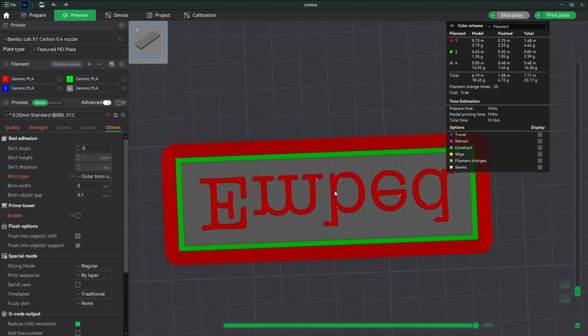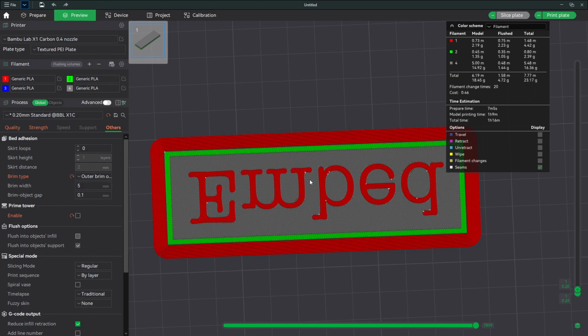It just depends. I had one earlier today I printed where I wanted to ensure that my white went down first so that when it came back and printed the black that went around it, which would be 2 layers, it would do, because it was only 2 colors on that first layer, I wanted the white to go down first. So it would do 1 layer, my first layer of white, switch to black, fill in the first layer, then immediately do the second layer of black, and then go off to do a color swap.